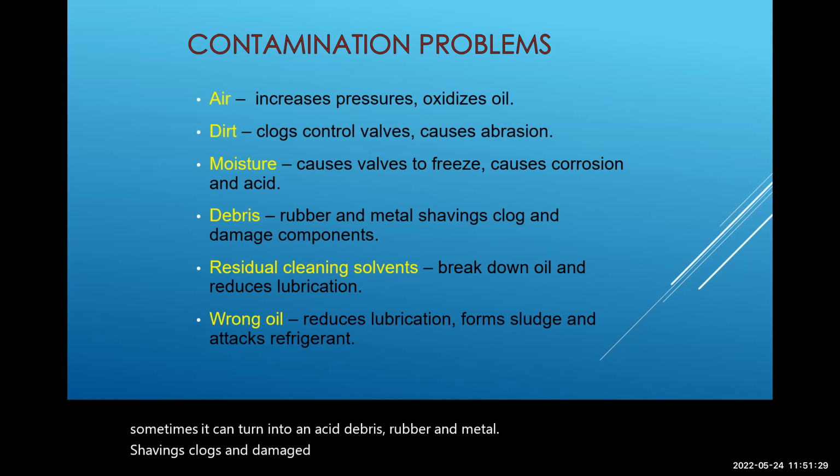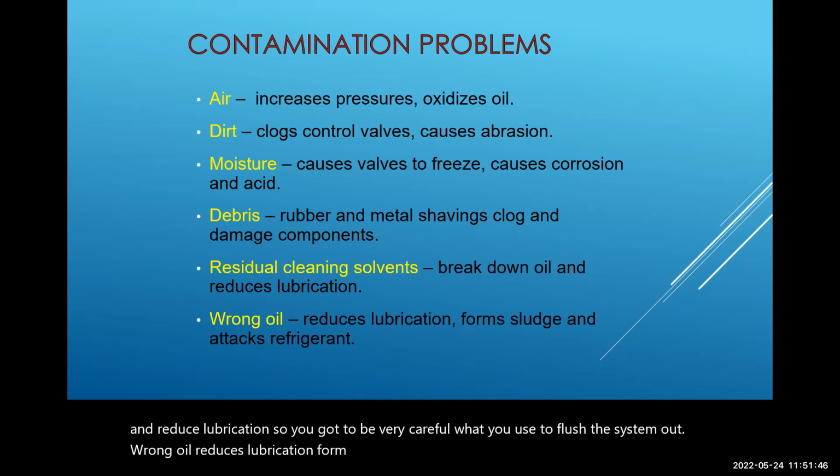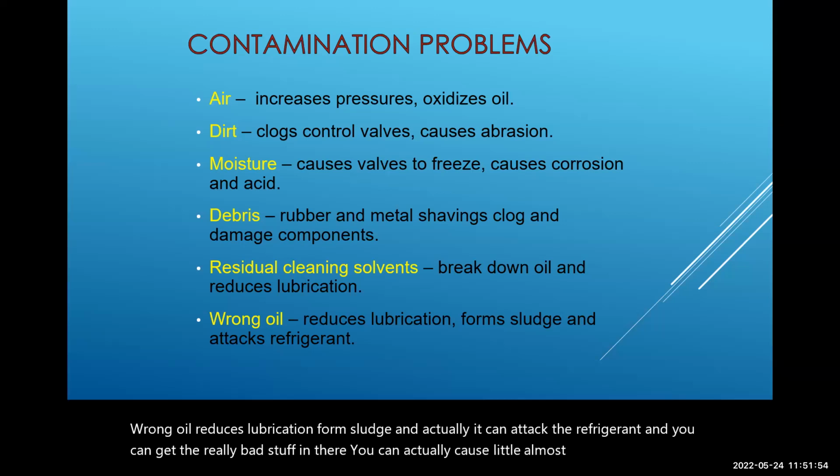Residue cleaning solution solvents break down oil and reduce lubrication. So you have to be very careful what you use to flush the system out. Wrong oil reduces lubrication, forms sludge, and it can actually attack the refrigerant. And you get really bad stuff in there. You can actually cause little, it almost looks like little balls.